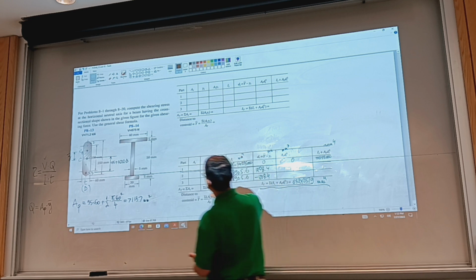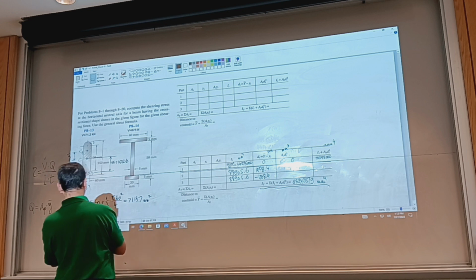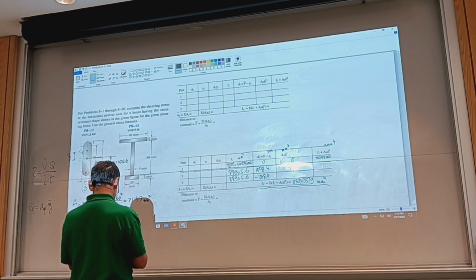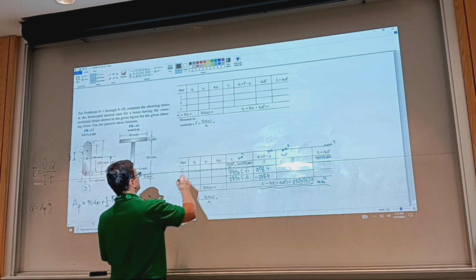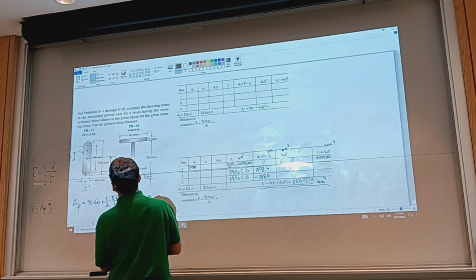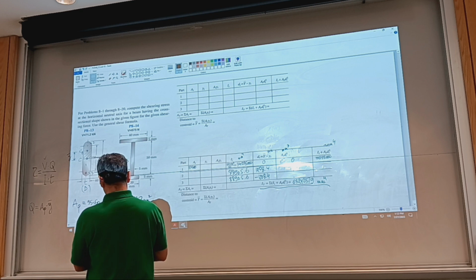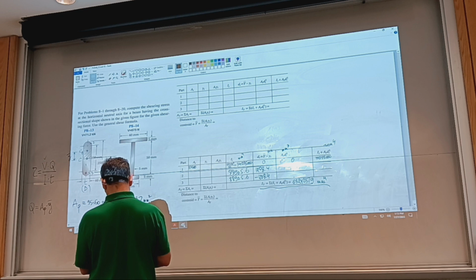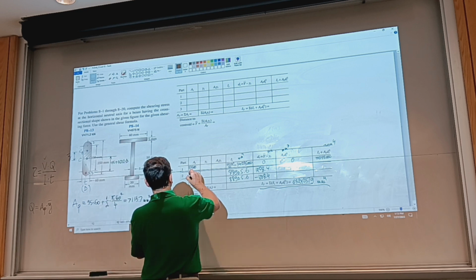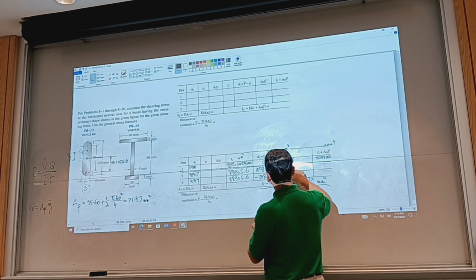So I never wrote the areas. Area for the first part is going to be 60 times 190, which is 11400. And then for the disc it would be essentially this piece here: pi times 60 squared over 8 equals 1413.7. Okay, so I can make the necessary corrections.